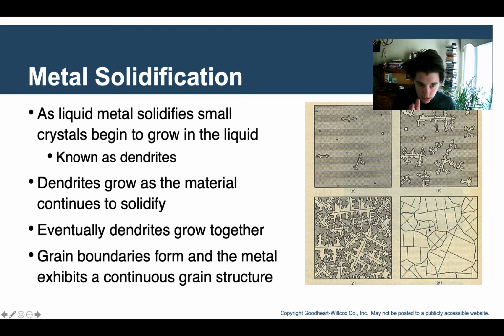This is like under a microscope. You would be able to see these big shapes under a microscope. This is the particular grain structure that this material has now. The important thing to remember is the boundaries between these large grains. The grain boundaries are where things happen, and it's something you have to keep in mind. So just hold these things in your head as we talk about this, so you know what's really happening and what you're dealing with.